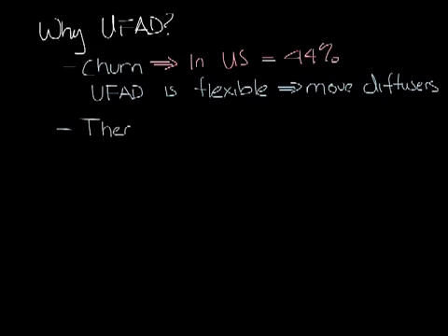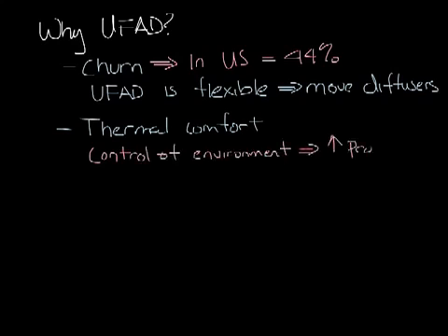Thermal comfort is another benefit to using a UFAD system. Studies have shown that when people have control over their environment, they're more productive. The individually adjustable underfloor diffusers allow occupants to control their airflow in their space.